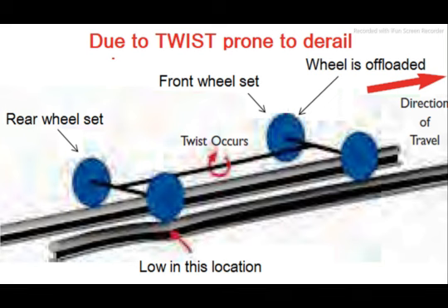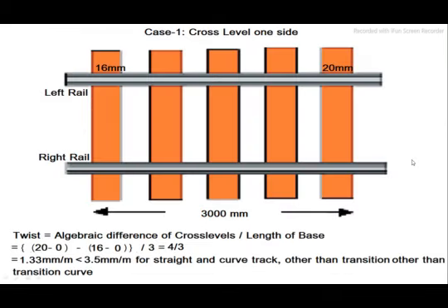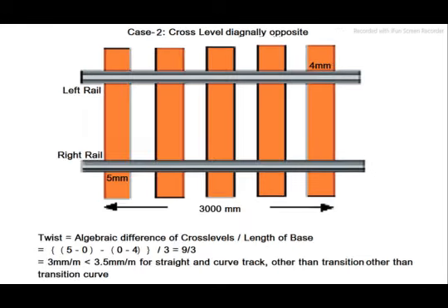In the transition portion of a curve, design twist is there for introducing or removing the superelevation in the circular portion of the curve. The above factors eat into the safety margin available on straight track against derailment. Any further defects in track parameters, vehicle defects and enginemanship might easily result in unsafe conditions for the vehicles.